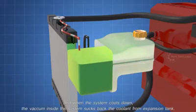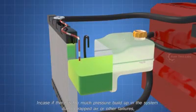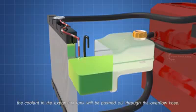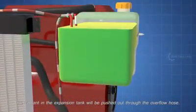And when the system cools down, the vacuum inside the system sucks back the coolant from the expansion tank. In case there is too much pressure build-up in the system, due to trapped air, or other failures, the coolant in the expansion tank will be pushed out through the overflow hose.